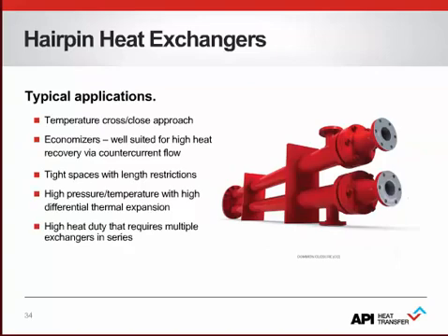The typical process applications that can take advantage of these design features are those that have a temperature cross, as one example. Process conditions that include a temperature cross typically require very long TEMA types or multiple units in series. Again, for reference, we define a temperature cross as when the hot side outlet temperature is lower than the cold side outlet temperature, and thus the temperature profiles of each fluid cross each other.